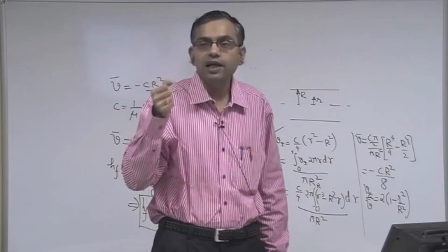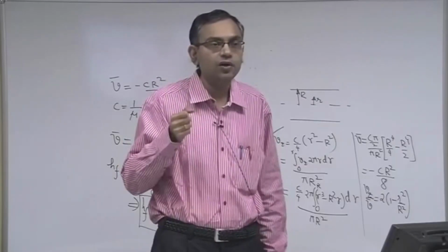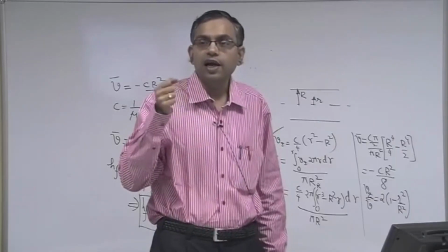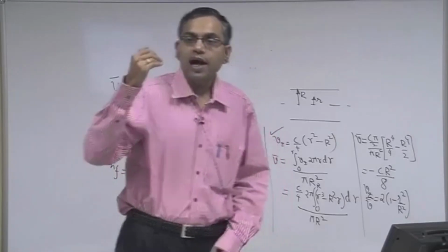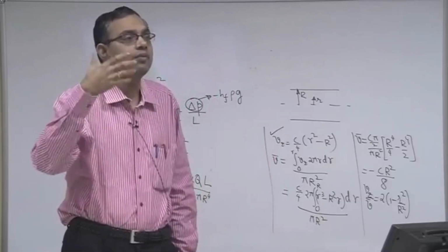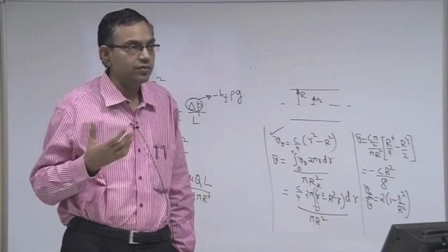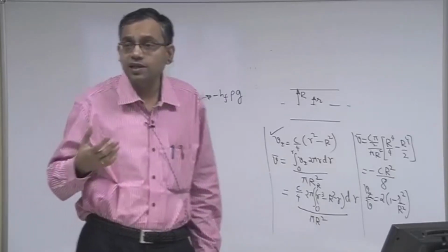So you will require tremendous pumping power to drive the flow. So you cannot really achieve that high a flow rate in a pressure driven microfluidic system which you can achieve in a macroscopic system. You have to compromise with the Q, because to achieve the same Q you require a huge driving pumping power. Therefore you compromise on Q, but sometimes it is a blessing in disguise.